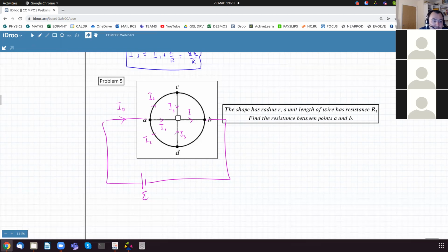Well, instead of writing I4, you can straight away write down I1 plus 2I3. I like to have fewer variables, and this one is going to be I2 minus I3, because I2 is coming in, some current is going here, and this is going to be I2 minus I3. Same here, I2 minus I3. And again, so this is I0.